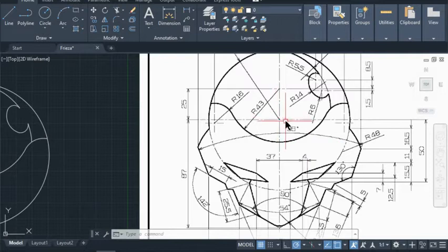You can see the distance from the center of the big circle down is 50. That whole thing is 50, and they have all the measurements here. You can see this is 16.5, that's 11, and that is 15.5. So the best way to do it is we're going to go ahead and offset this. We're going to draw something here perpendicular to the other construction line, and then we're going to offset it all the way down 50, and then we go up 15.5, we go up 11, and then we go up 16.5. That will give us the remaining section, and that is the location where that arc ends right there.